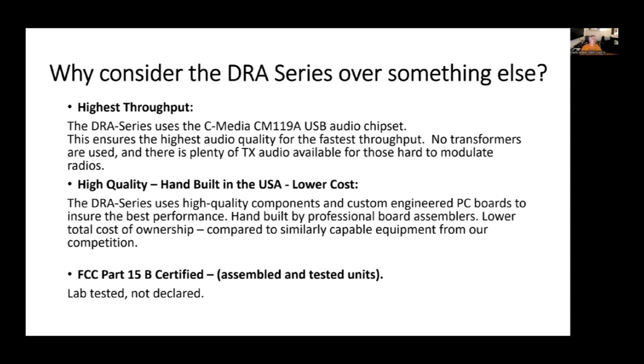When all that you have is Vox to create the push to talk, there is an inherent delay for the radio interface to realize that there's audio, understand that there is, and then create the push to talk, and then that has to make the radio transmit. There is an inherent delay in doing that. There's also a delay whenever the audio disappears, that the Vox has to say, oh, the audio's now disappeared, I probably should shut the transceiver off, shut the transmitter down.